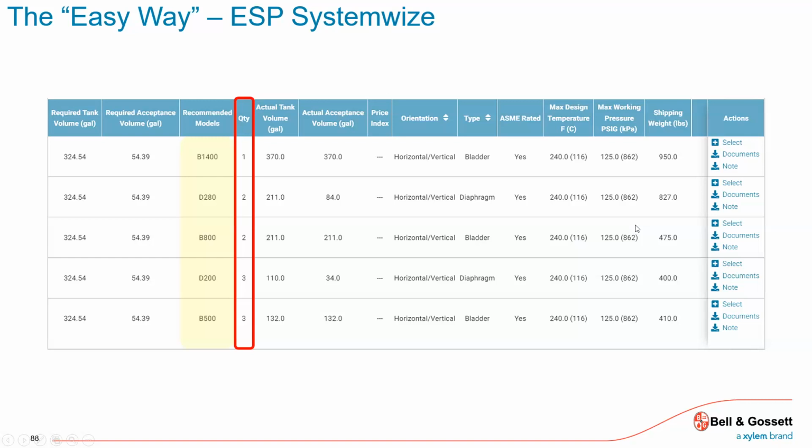But just be aware that whether you're going with these 3 smaller or the one big or the 2 different style diaphragm, at the end of the day, what's my expanded volume? And then what's my total tank volume? And how that's determined is what is my fill pressure when I start and what's my relief valve. That's my pressure range I get to play with. And the greater the range, the smaller the tank. The tighter, the bigger the tank to accept that.